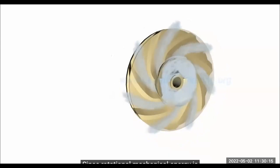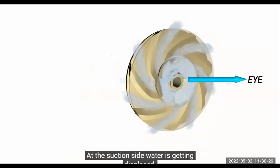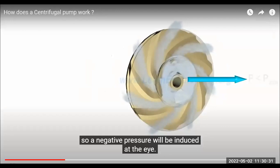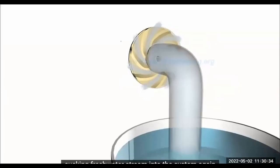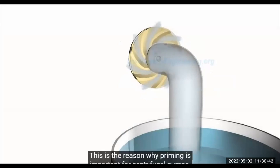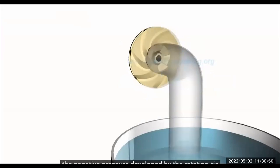Since rotational mechanical energy is transferred to the fluid, at discharge side of impeller, both pressure and kinetic energy of water will rise. At suction side, water is getting displaced, so a negative pressure will be induced at the eye. Such low pressure helps in sucking fresh water stream into the system again, and this process continues. This is the reason why priming is important for centrifugal pumps. If no water is present initially, the negative pressure developed by rotating air at eye of impeller will be negligibly small to suck fresh stream of water.